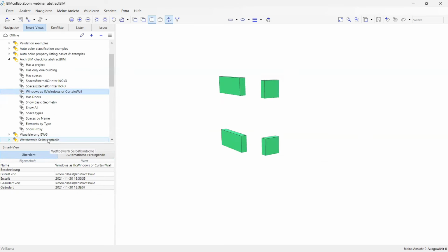I just quickly go through to get an idea, because what we see is that most of the time when something goes wrong, the spaces are missing. So that's mistake number one with all the uploads we are seeing. Can you repeat that one more time? Yes, missing IFC spaces. So models without IFC spaces. And without them, we can't do anything. Well, architectural models, right? Yes. In the other ones, I don't care.